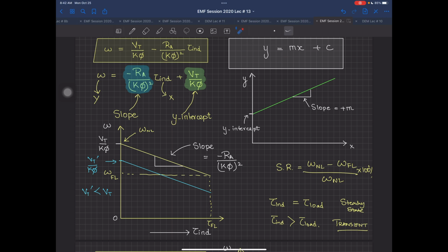And this speed torque equation is telling you that your shunt motor or separately excited motor exhibits a negative slope and certainly a positive speed regulation. Why positive? Because certainly omega no load is greater than omega full load. If this characteristic was something like this, then certainly you would say that your speed regulation was negative. Why? Because then at no load the speed was smaller, and at full load it would be larger. But there is only one machine which we'll be discussing in the next lecture. So the speed regulation for shunt machine and separately excited motor is positive, and this is the characteristic curve.